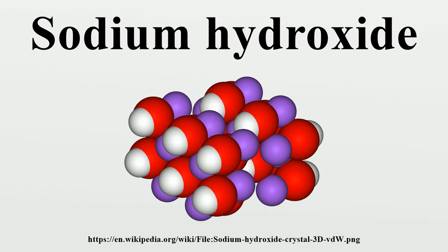Aluminium hydroxide is used as a gelatinous flocculant to filter out particulate matter in water treatment. Aluminium hydroxide is prepared at the treatment plant from aluminium sulfate by reacting it with sodium hydroxide or carbonate: Al2(SO4)3 + 6NaOH → 2Al(OH)3 + 3Na2SO4; Al2(SO4)3 + 6NaHCO3 → 2Al(OH)3 + 3Na2SO4 + 6CO2.